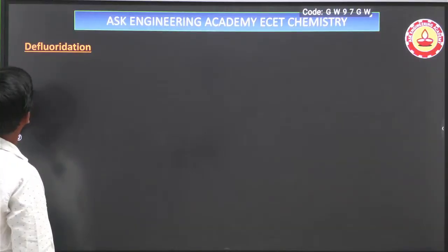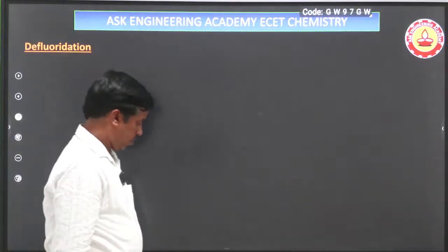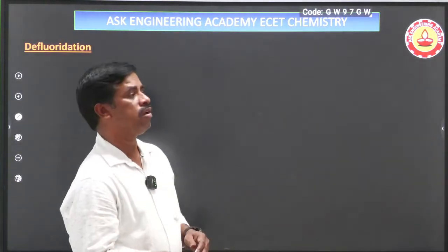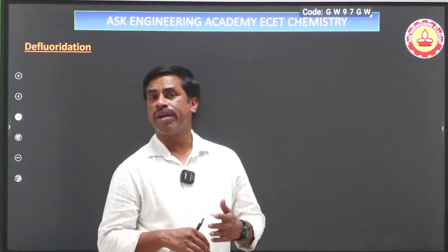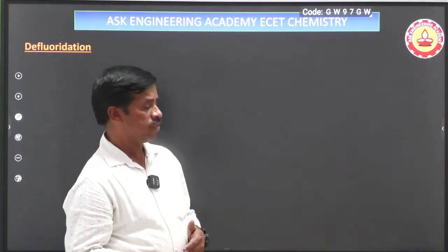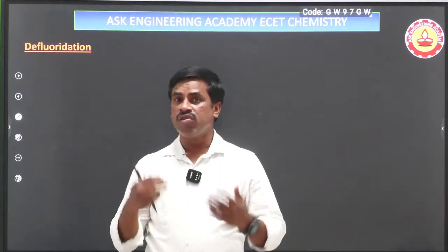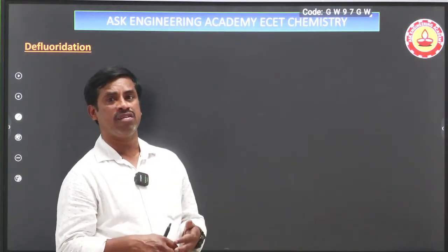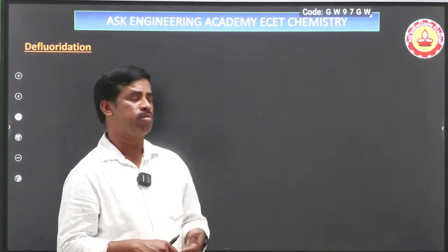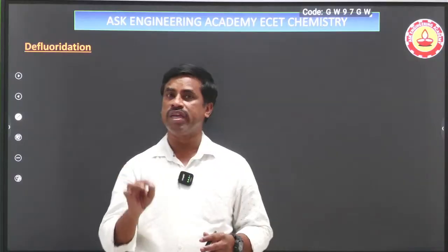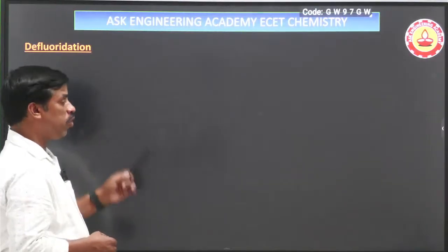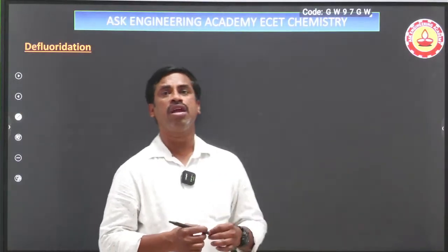Next, defluoridation. This is the last topic. Defluoridation means the process of removing dissolved fluoride from water, or minimizing the dissolved fluorine in water, or maintaining a minimum level, below 2 ppm fluorine in water, is said to be defluoridation. This defluoridation method is explained by the Nalgonda technique.